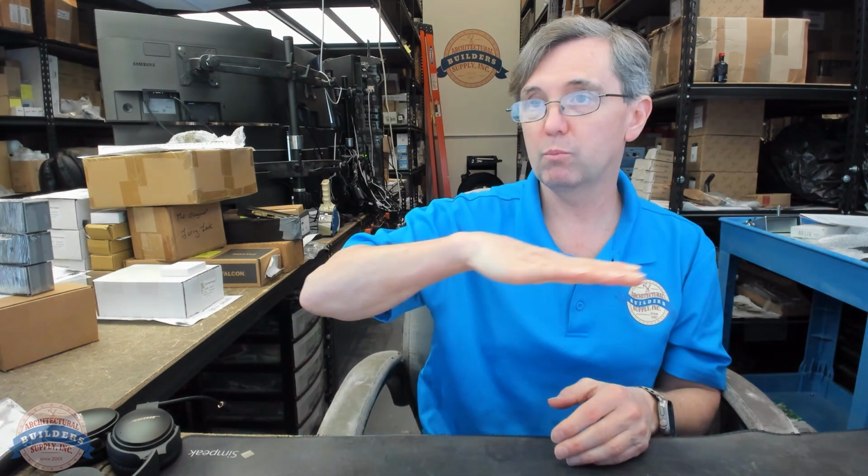So if you're doing a retail space, I've done these where they want an STC rated door but don't want to pay for an STC rating, I would now be telling the client, don't do polystyrene, do honeycomb. If it's a mechanical room, you're not going to be going in and out a lot, and if it was an exterior door that may be more important for STC rating, I might just recommend a closed or a sealed top cap, or I might personally get in there with silicone caulk and seal all of that. So again, score, honeycomb 1, polystyrene 0. Let's move on to polyurethane because that's the next one in my list.